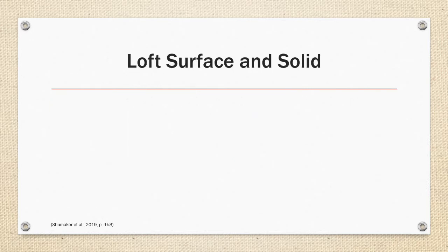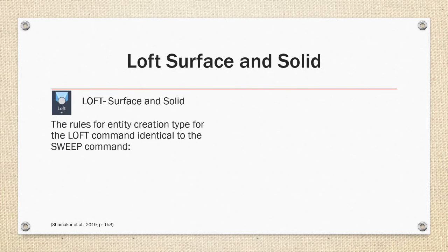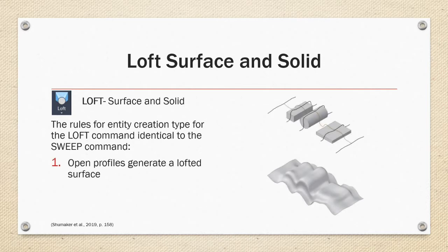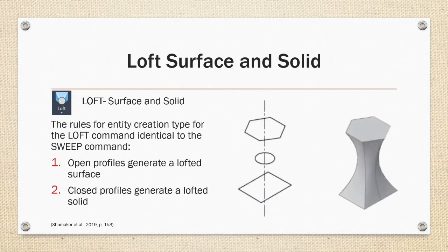The loft command in AutoCAD can produce both surfaces and solids, just like the sweep command, which has identical rules: 1. Open profiles generate lofted surfaces, and 2. Closed profiles generate lofted solids.